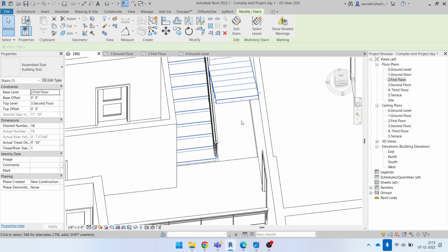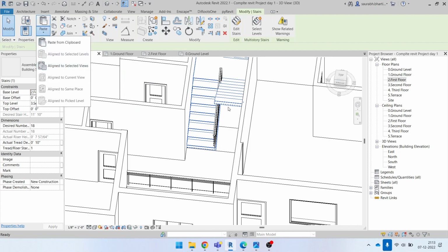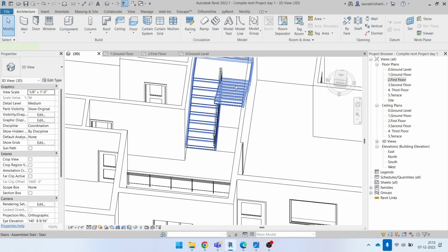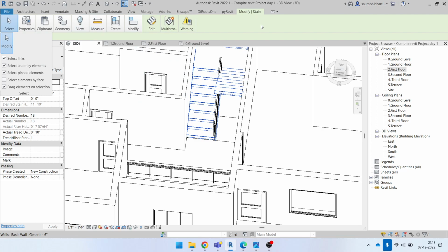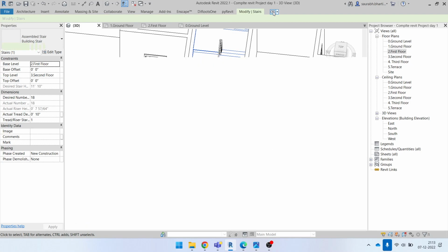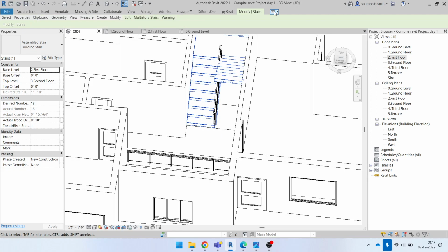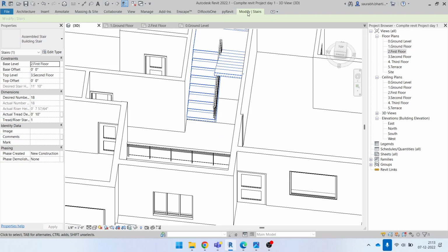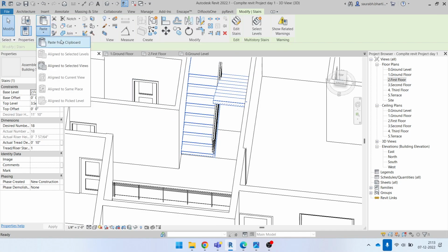Now what I'm going to do is select our stair that we have drawn here. I will go to copy and then try to paste it. So select it, go to modify. Here, in case sometimes, this is what I have not told you about. In case you have got something like this, that compacted view, you can always click here and change the type of view. So this is where we were, and sometimes by default you can click it over this side and you will just lose everything. So you can just click it here and get it back. So I'm just copying it and then paste.